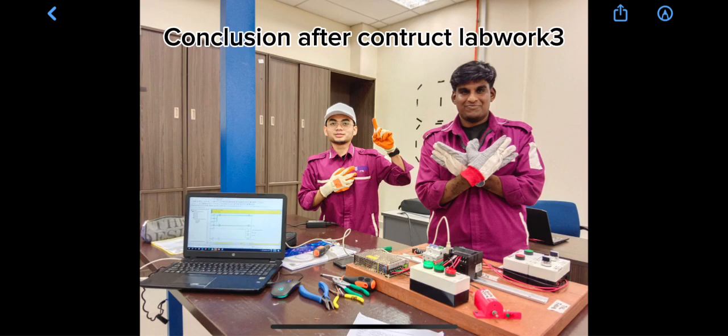Other than that, I am also able to design, compile, debug and download the PT program to the human machine interface (HMI) touchscreen unit by using Omron NB Designer version 1.5 software. After that, by using CX Programmer also, I am able to design, compile, debug and transfer the ladder diagram to the PLC CP1E. And lastly, I also see the difference between the CP1E E20 and CP1E N20.